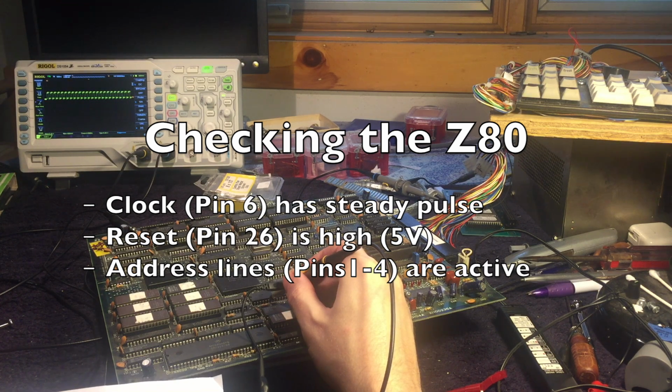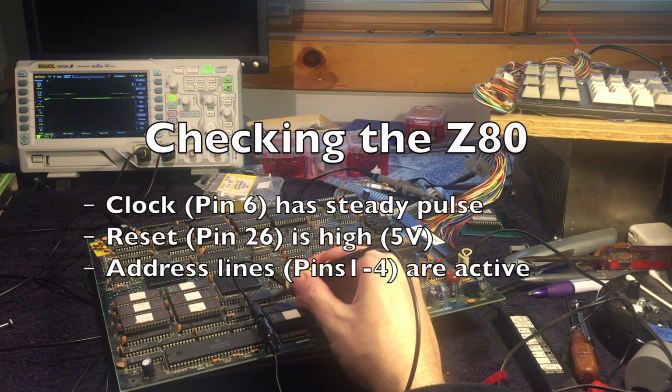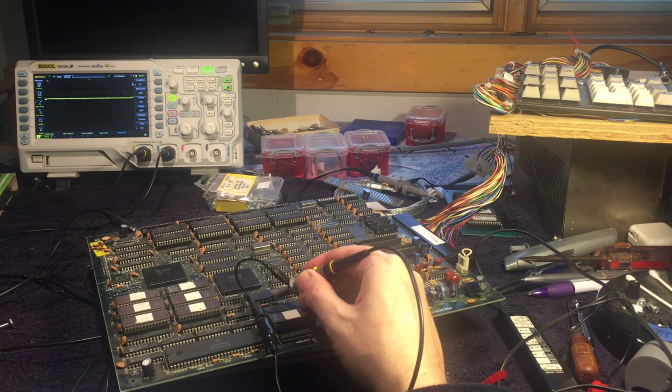We got a clock, and let's make sure reset is not active. Reset is high, so that's good. There is activity on the address bus, so the Z80 CPU is at least functioning.